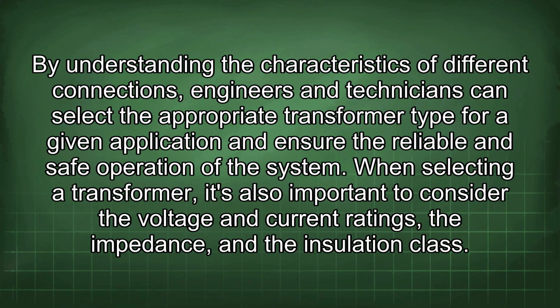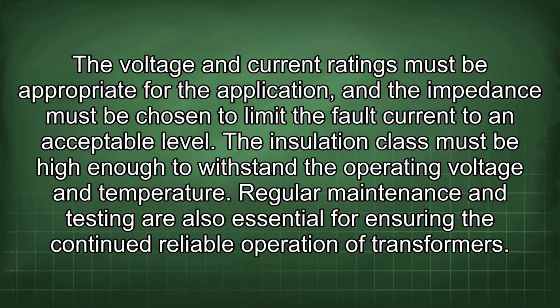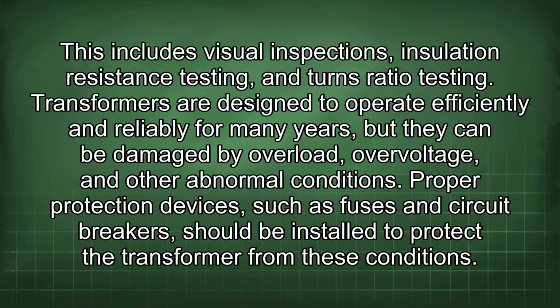When selecting a transformer, it's also important to consider the voltage and current ratings, the impedance, and the insulation class. The voltage and current ratings must be appropriate for the application, and the impedance must be chosen to limit the fault current to an acceptable level. The insulation class must be high enough to withstand the operating voltage and temperature. Regular maintenance and testing are also essential for ensuring the continued reliable operation of transformers. This includes visual inspections, insulation resistance testing, and turns ratio testing.